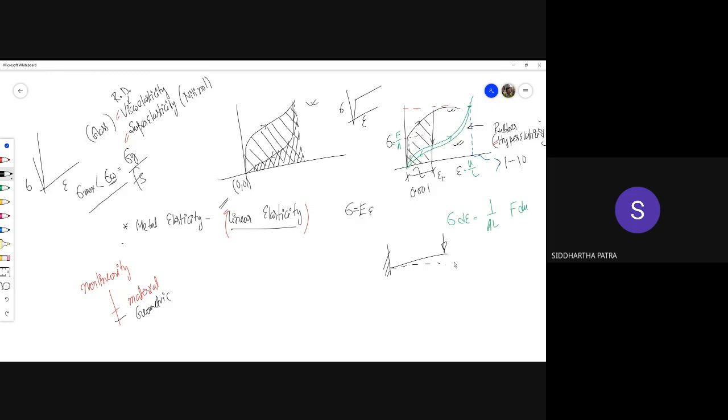But when we change the 100 Newton load to 200 Newton, we do not consider the amount of deflection that has been continuously happening from 0 to 100 Newton. We still consider the geometry to be flat, and we just apply the 200 Newton load, and we assume that the deflection would be twice if we change the load to twice. See, for us, this is PL cubed by 3EI.